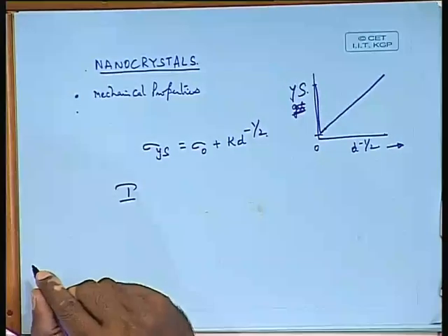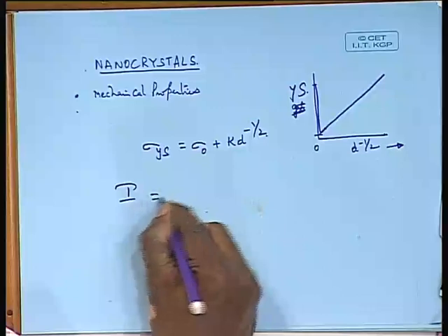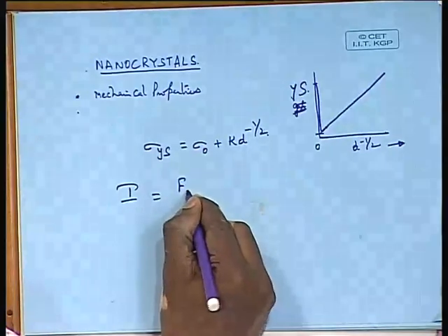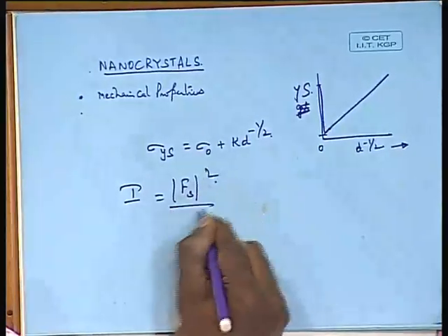If you compare the diffraction patterns of these 2 by X-ray, you will not be able to see any difference, basically because copper and zinc are next to each other in the periodic table, and the atomic number difference between these 2 is just 1. So, if you consider the structure factor, the difference is basically 1. If you talk of the intensity, intensity is nothing but the square of the structure factor of the superlattice reflection by that of the fundamental reflection.